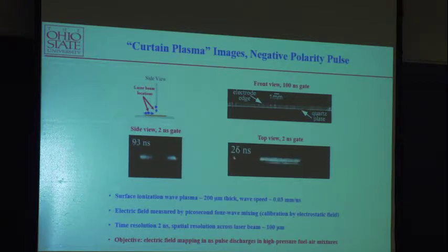So what it says is that with this method, they try to generate a high pressure discharge in a high pressure fuel mixture, because high pressure plasma easily transitions into a thermal plasma. Not only do you need a very small gap, but you also need a very short pulse to avoid the transformation from a non-equilibrium plasma to a thermal plasma.